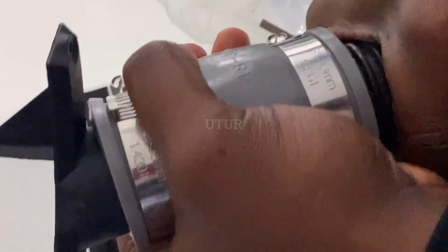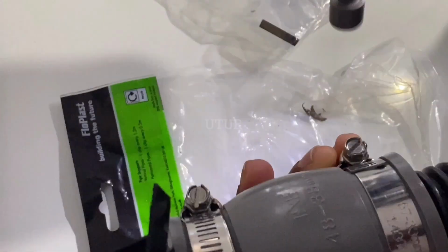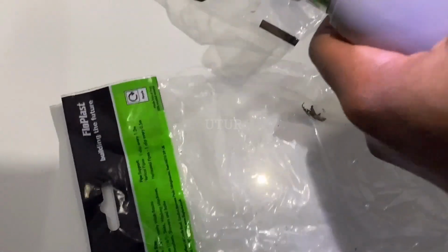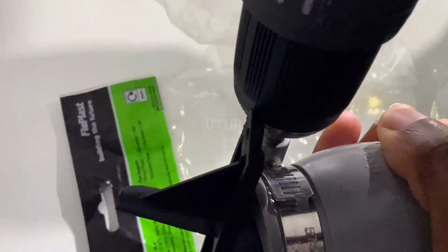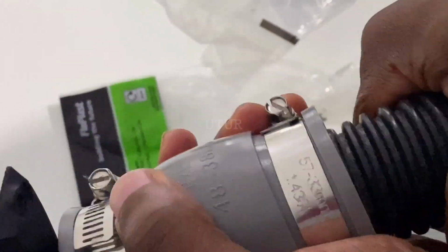If your vacuum adapter connection and your flexible hose is loose, torque tighten further. But always visually inspect and test the firmness of the connection by pulling out or pushing out the flexible hose and the vacuum adapter, just to make sure that you've got a sturdy and tight fit connection. Okay, but pull on the trigger of the drill gradually and not with maximum force.